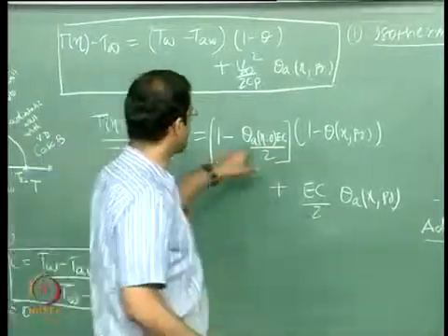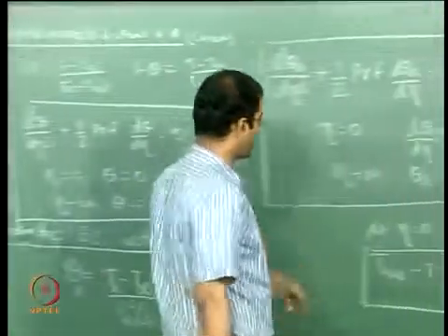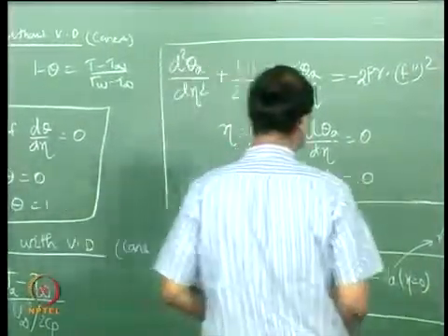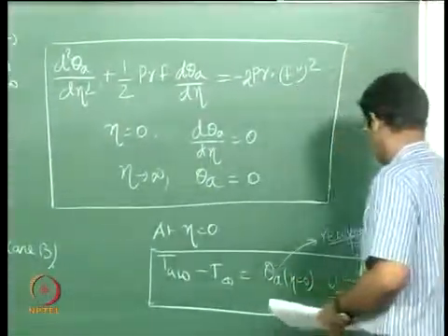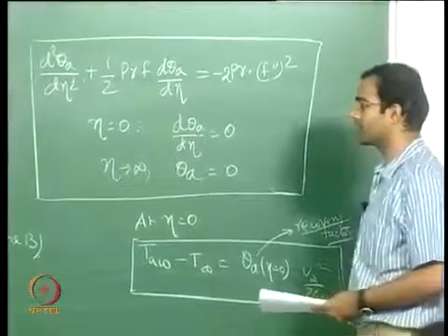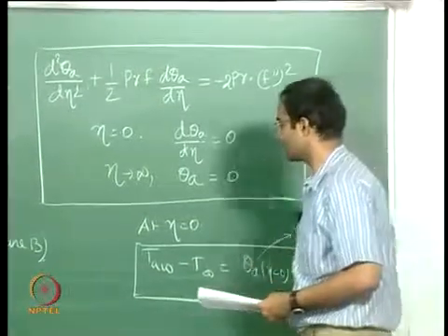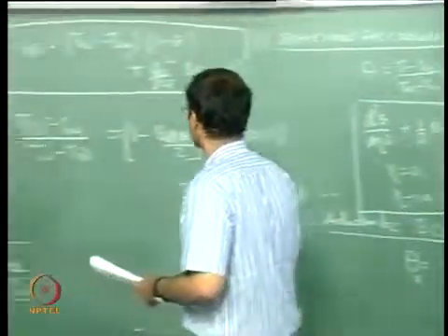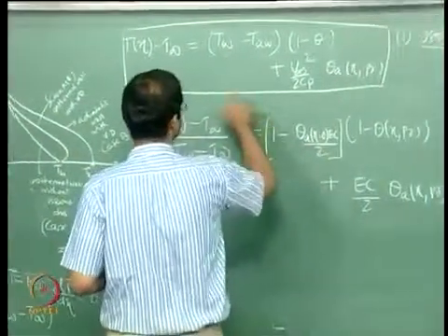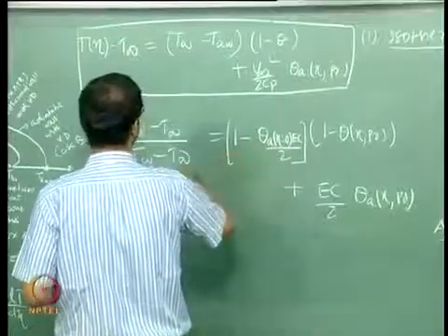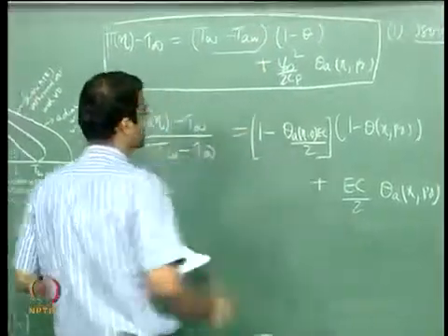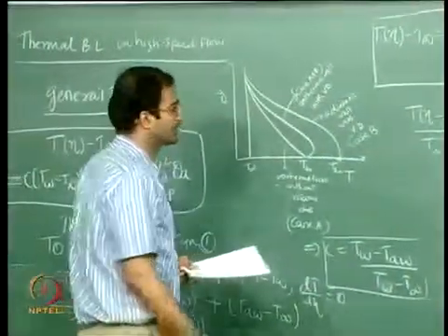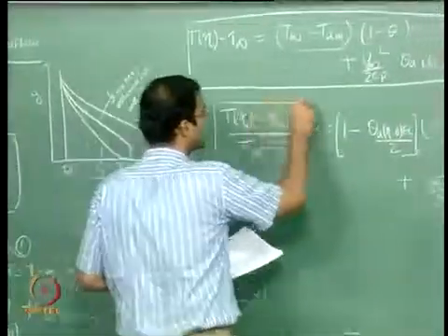Okay, because theta a and Eckert number is basically this term. Eckert number is u infinity square by Cp delta T into this. So that will be T adiabatic wall minus T infinity. So you can say 1 minus this divided by T wall minus T infinity will give you this finally. You can just check that. Okay, so this is your final non-dimensional solution.